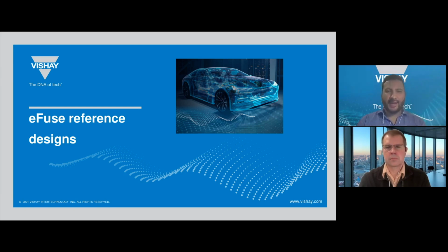But for others, like the gate resistor, the MELF that doesn't have such a high accuracy was selected as well. So it really varies on the application of the circuit. But like I mentioned, Vishay has all the different resistors with all the different accuracies needed for specific applications.